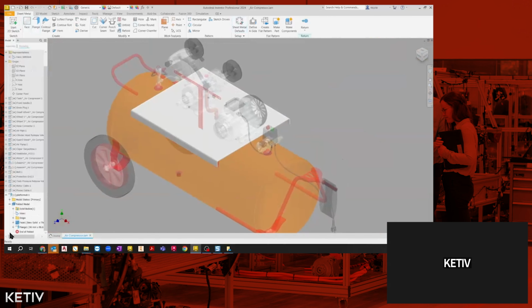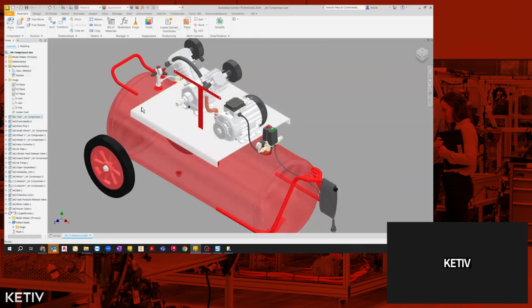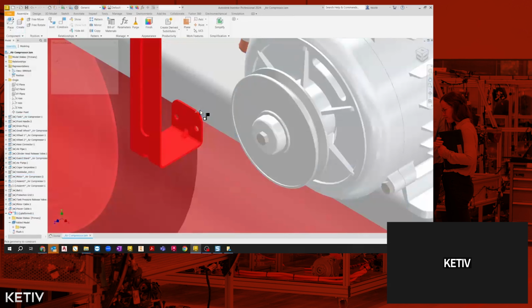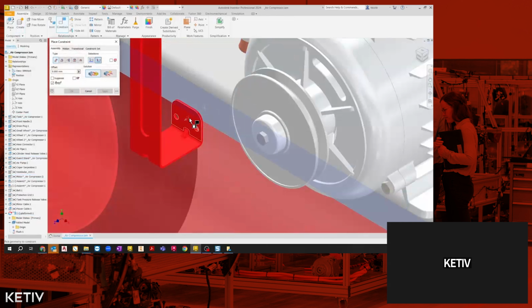She's going to make her face adaptive here, which makes the corresponding sketch and sheet metal part adaptive as well. She can now jump up to the top level assembly and move around and constrain her mounting base as needed. So we'll see as she does that.